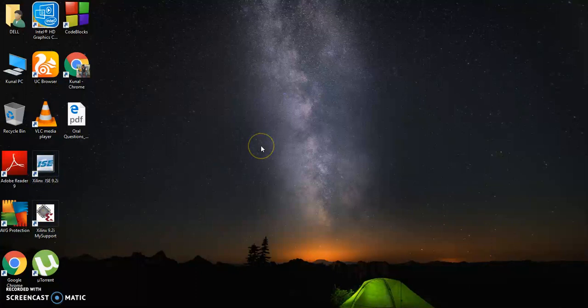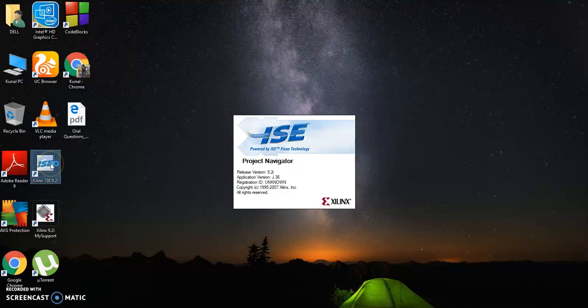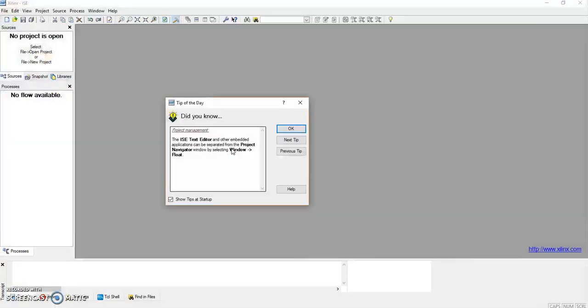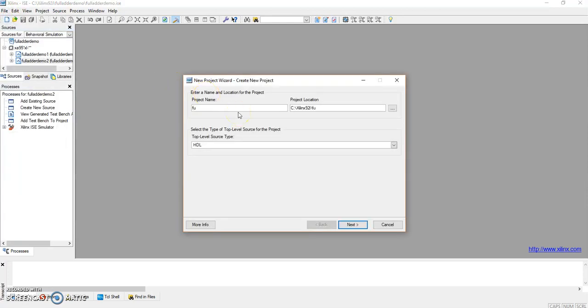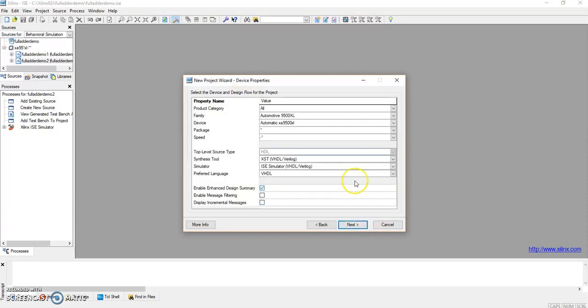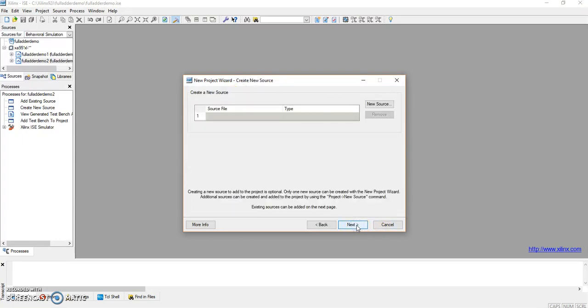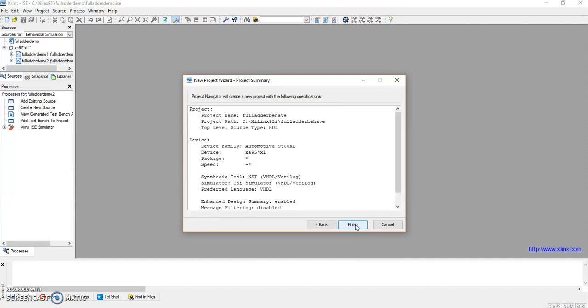So the next video is of full adder behavioral model style. We open Xilinx. Again, then after opening Xilinx, we click on new project, full adder behavioral. HDL, the language is VHDL. Next, next, and next. Finish.